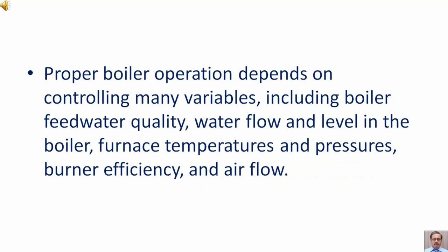Proper boiler operation depends on controlling many variables, including boiler feed water quality, water flow, and level in the boiler, furnace temperatures and pressures, burner efficiency, and air flow.